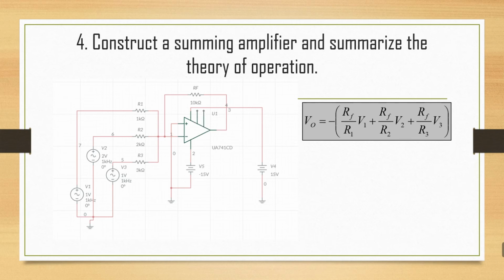For information, on the basis of the op amp, the most commonly used summing amplifier is an extension of the inverting amplifier configuration. Multiple inputs are applied to the inverting input terminal of the op amp, whilst the non-inverting input terminal is connected to the ground. Due to this configuration, the output of the voltage adder circuit is out of phase by 180 degrees with respect to the input.